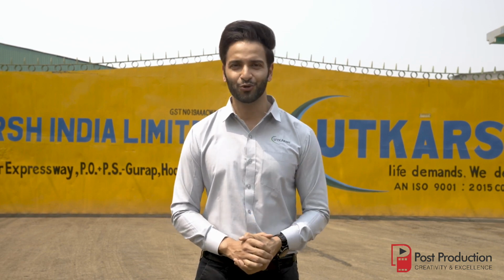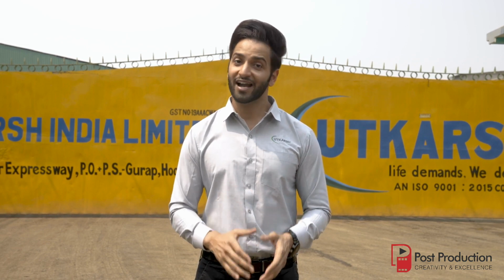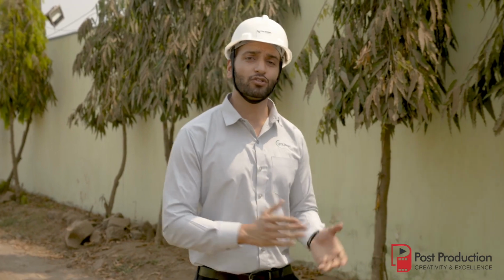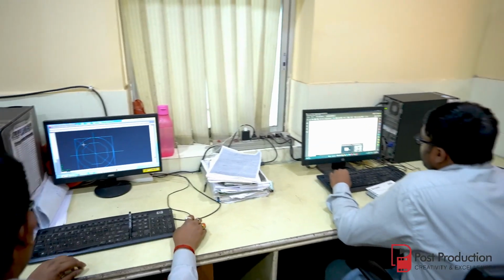Today I am going to show you how high masts are erected and finally installed at client's facility. We have two functions in course of high mast installation: civil foundation and erection. We start foundation drawings by keeping the following parameters in mind. A. Wind speed of the location where the high mast is being installed, and B. The soil bearing capacity of the ground where the installation is conducted.